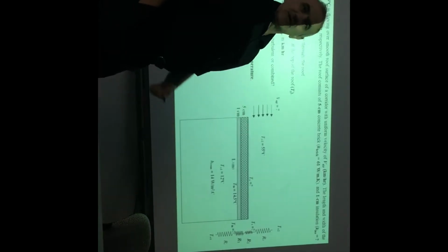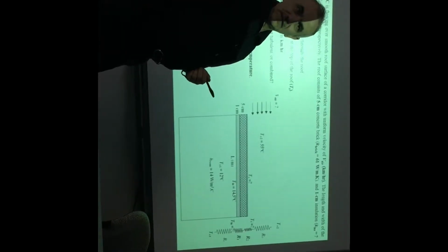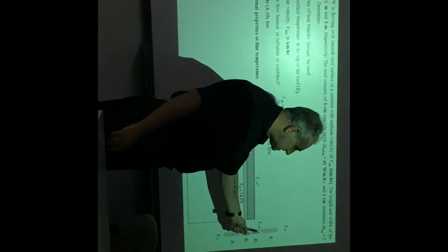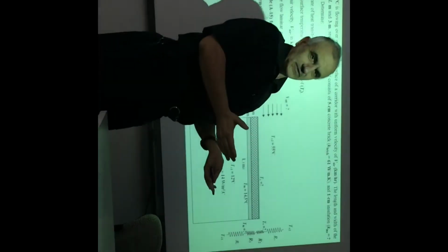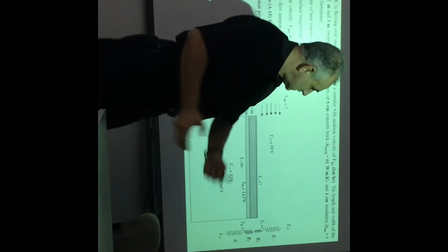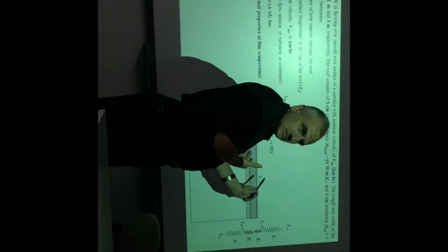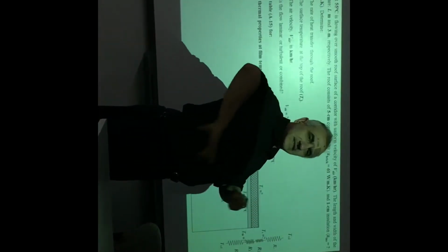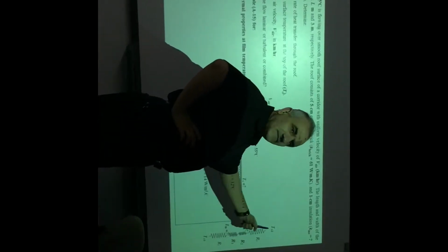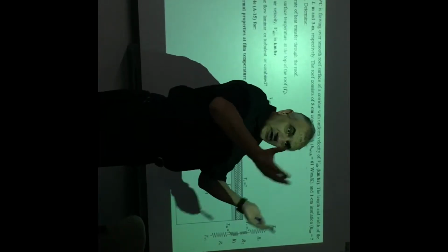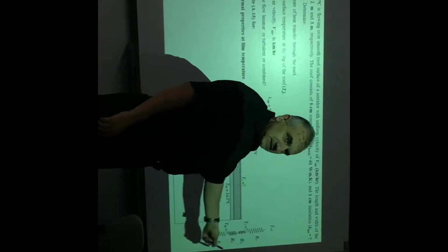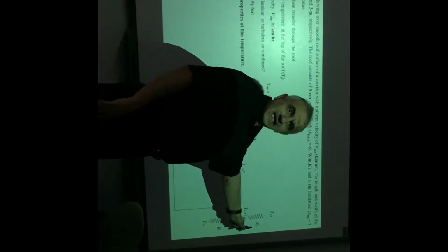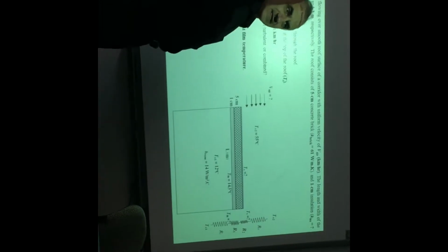So the resistance outside, you can't find it directly. Now the resistance is unknown. Delta T over resistance. T fluid 1 minus T surface over resistance is equal to Q. Right? Q known. T fluid 1 known. T surface known. Or apply T fluid 1 minus T fluid 2 over total resistance. T fluid 1 and T fluid 2, both of them given. Q known. So you can find the total resistance. Minus 1, 2, 3, you come up with the unknown resistance. The unknown resistance is 1 over hA.